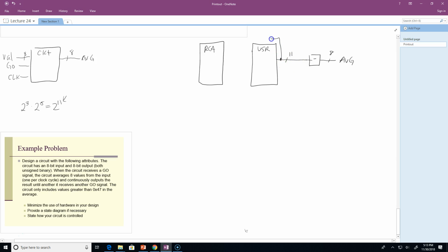And remember, I'm not really putting a lot of thought into this yet because it's an accumulator. I've done this many times and I don't really have to think about it. Okay, looking good there. Sum here, 11 bits, 11 bits. And this is the data. This is a clocked value. And this is my typical shift register with a select. Okay, let's fill that in.